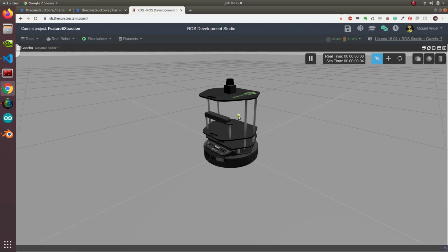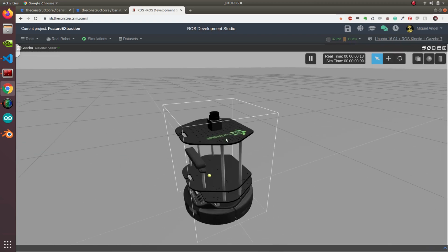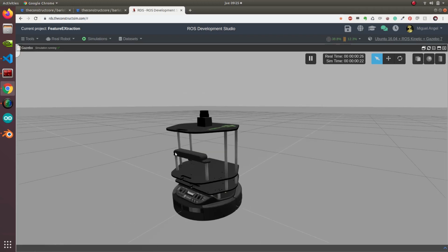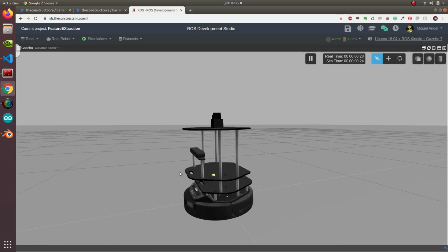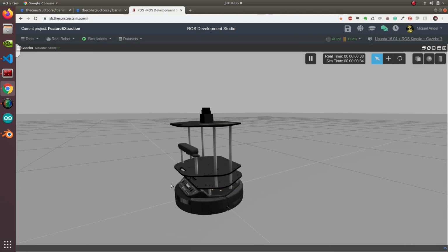So essentially what we need to do is several things. One, this design of TurtleBot has the laser on the top, so we'll have to move it to the bottom so we have this space free to place objects on top. Also, we don't need the Kinect, so we won't use that. And then we will try to close this part where all the ports and this kind of stuff are, so that it looks a bit more professional, a bit cleaner.